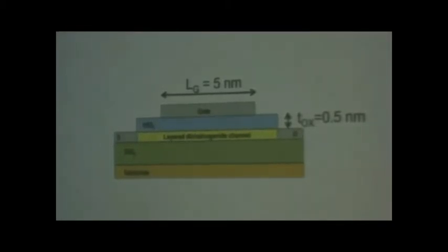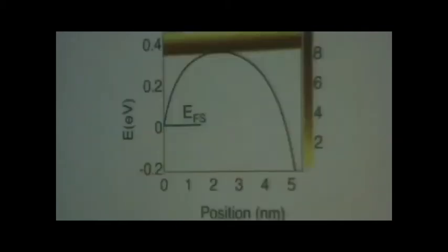So this is why, when I'm saying that, let's assume that my source and drain are very good, I'm putting so much charge into the system that I cannot actually go beyond 1 monolayer. Okay, and so this is the thing, that we want to improve the contact resistance, but when we go to the limit, it looks like we cannot go beyond 1 monolayer.